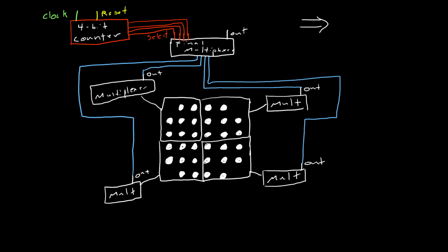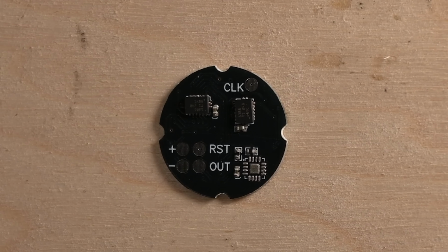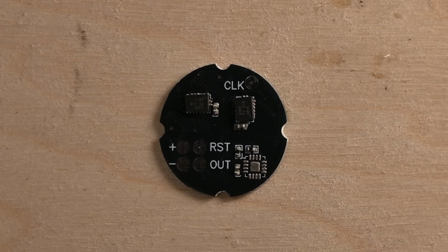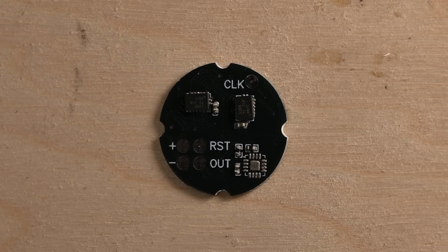It is now impossible to know which exact pin is selected, so another connection can be used to send a reset pulse to sync. Now there are a total of 3 connections to the microcontroller: the analog input, the counter incrementer, and the counter reset. It is also important to mention that on the second board, there is an op-amp to amplify the voltage to 5 volts from the incoming neuron, since they typically send pulses of only about 0.15 volts.